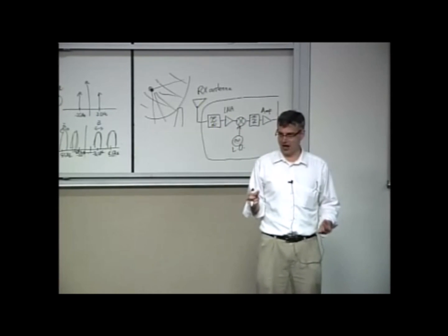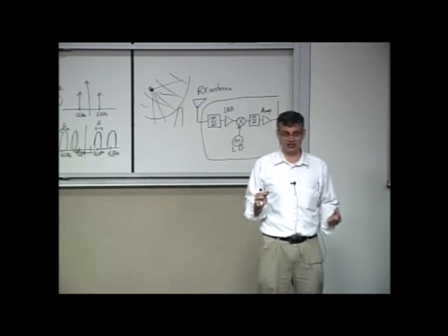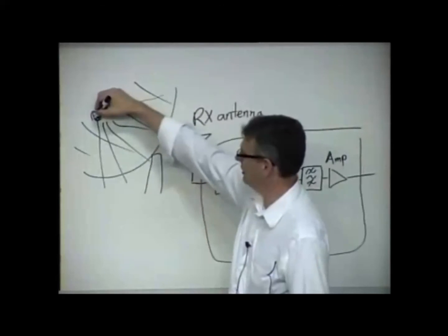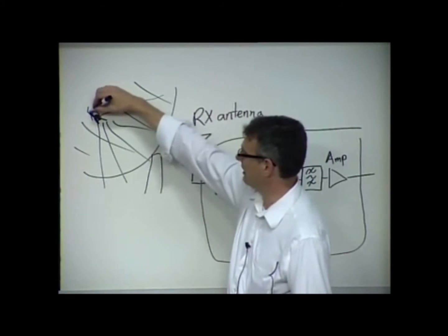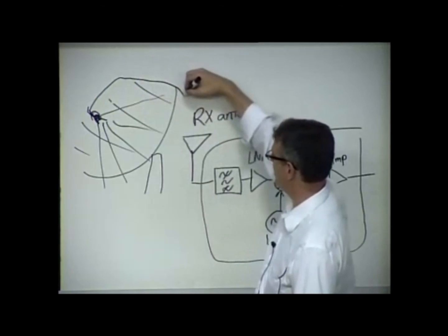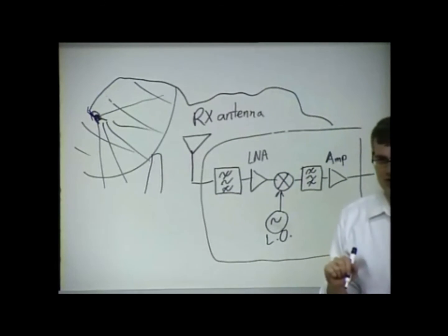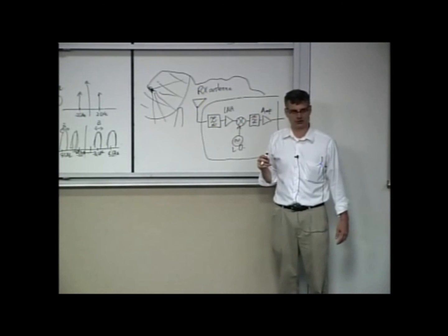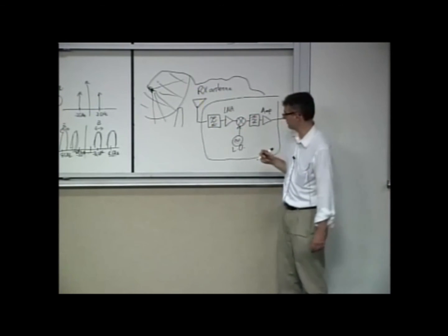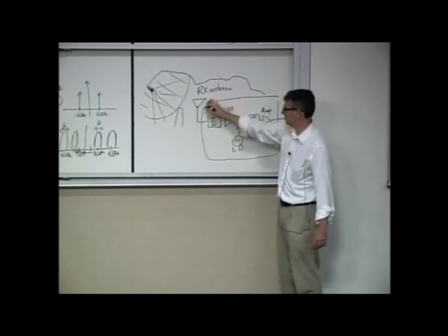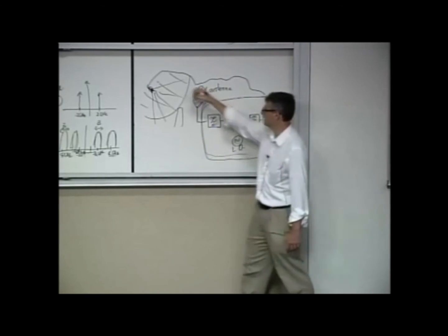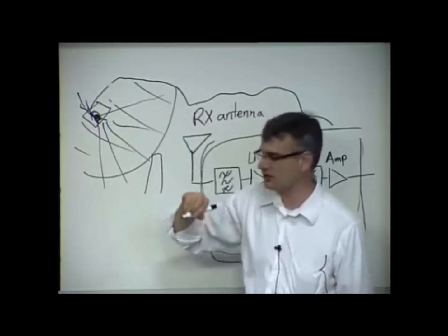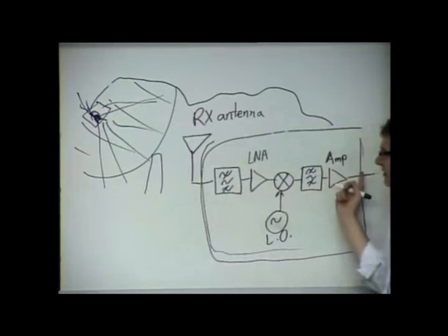You can use waveguide, but even waveguide at 60 gigahertz is really lossy. And it's not particularly convenient to put a little horn antenna at 60 gigahertz or any millimeter waves and then use your erector set of waveguides to route this to your little communication shed. Waveguide is not a very low-cost or flexible medium to do your signal transport. So as a result, usually you put something like this, when you're doing high-frequency reception, at the front feed line. You've got to run some DC power to this because there are active components here.